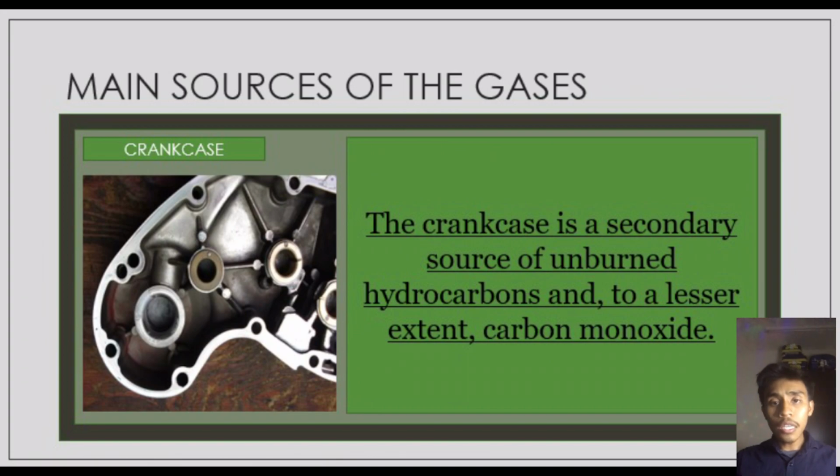Secondly is the crankcase. The crankcase is the housing for the crankshaft in the reciprocating internal combustion engine. In most modern engines, the crankcase is integrated into the engine block. Four-stroke engines typically have an oil sump at the bottom of the crankcase, and the majority of the engine oil is held within the crankcase. The crankcase is a secondary source of unburned hydrocarbon and, to a lesser extent, carbon monoxide.